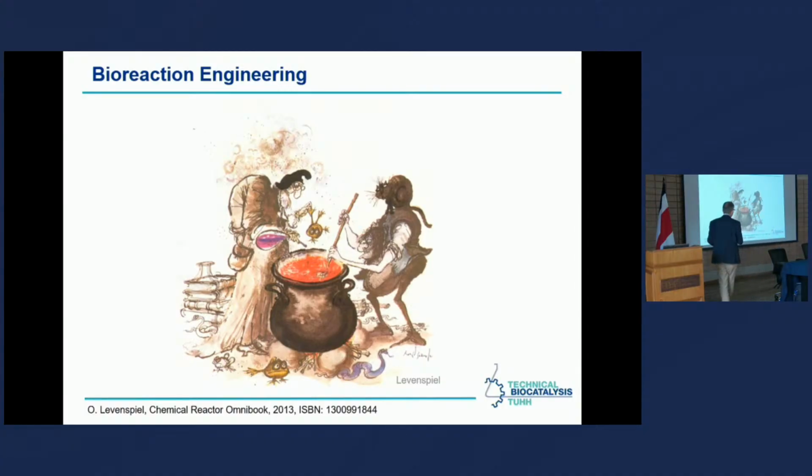So for one, we need energy input. And energy input comes from fire, from heat below. But we also have energy input by the stirrer stirring the soup. This is what we call a batch reaction. We insert everything at time point 0, and then we heat it and we stir it. And normally, in a process, we like to control the temperature, so we thermostat it to have a defined temperature.